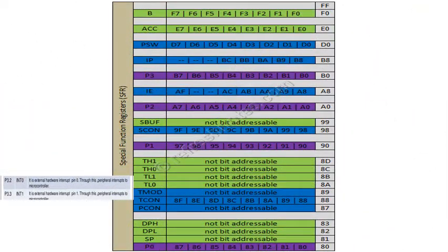Let us say your microcontroller is busy performing some mathematical operations, and in the middle of that some actuators need to be serviced. In such a case, external interrupts come in handy. An interrupt in essence is a way of stopping the microcontroller's current operation and making it perform some other task due to higher importance. The 8051 microcontroller has two external interrupt ports, P3.2 and P3.3, to manage external devices of